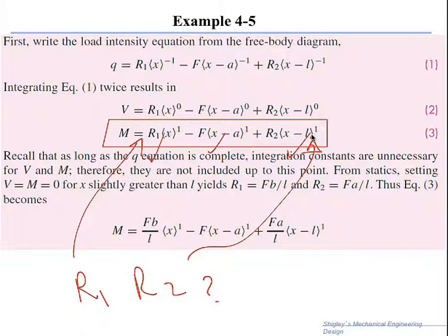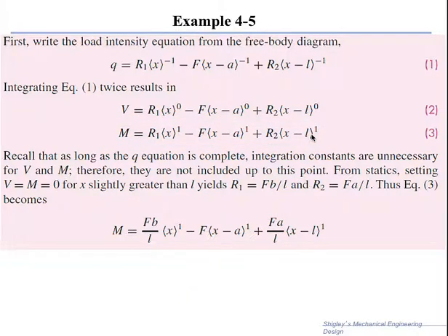Now I can do this two ways. One is to use statics, and in order for me to use statics, I just write two equations and two unknowns. One is the force equilibrium equation, and the other one is the moment equilibrium equation. I will obtain R1 and R2.